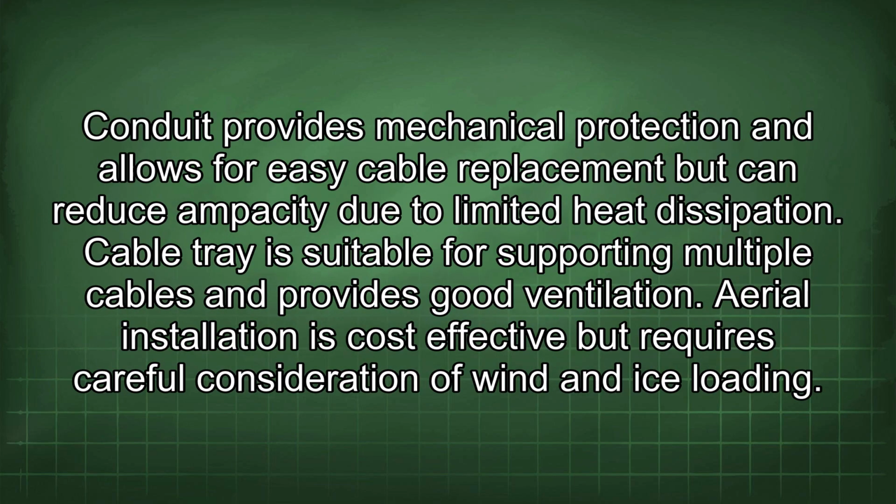Conduit provides mechanical protection and allows for easy cable replacement, but can reduce ampacity due to limited heat dissipation. Cable tray is suitable for supporting multiple cables and provides good ventilation. Aerial installation is cost-effective, but requires careful consideration of wind and ice loading.